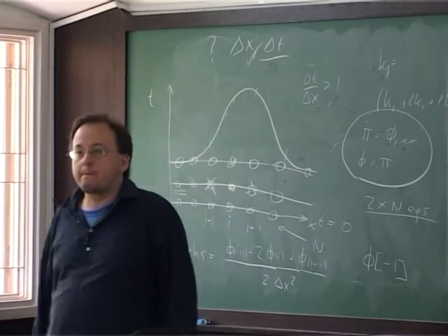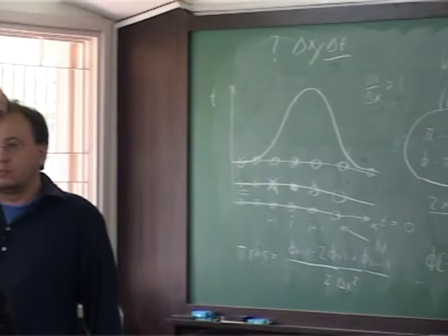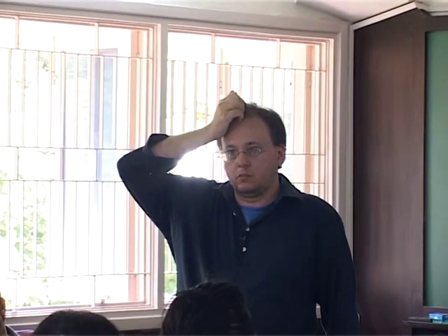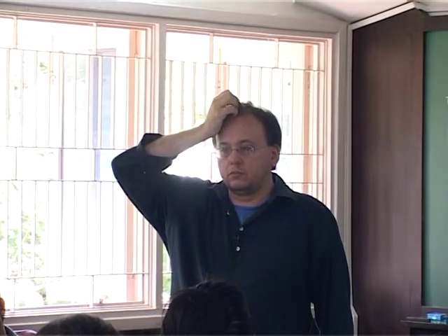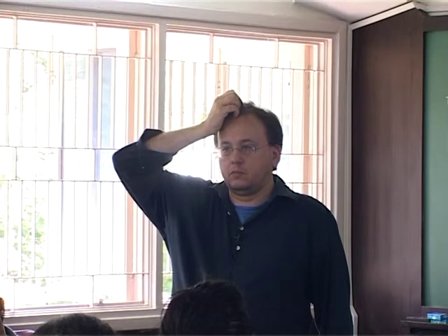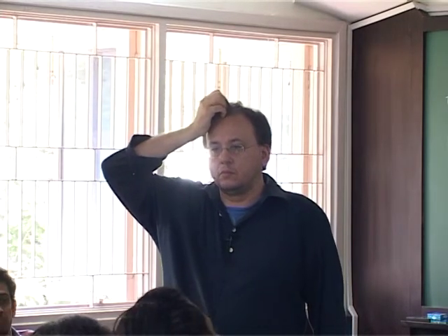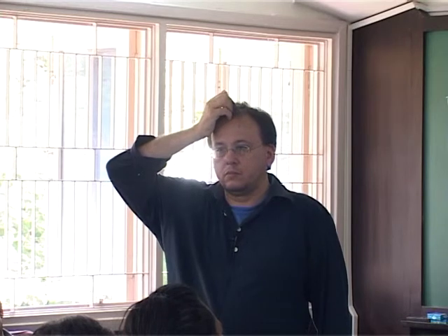So the question I asked you yesterday also. Suppose you have different velocity. Velocity is time dependent. Now your CFL condition also changes according to that. Right, exactly. Suppose you want to take the maximum advantage of the computation power. So suppose you take some delta t. Now according to the CFL condition, you can change the delta t according to velocity. And now, how can you be sure that this changing of delta t does not affect your energy?